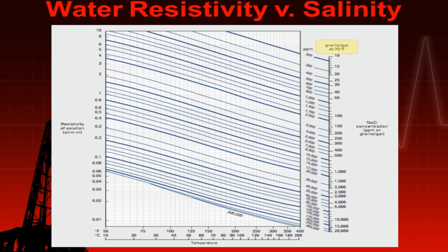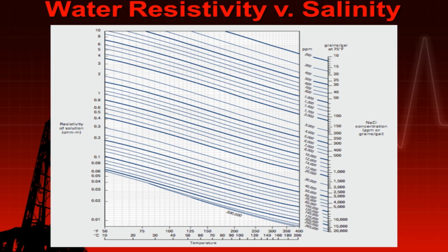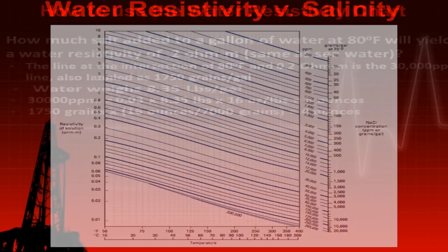So over here you've got this in grains per gallon. So I looked it up. I don't remember this very frequently, but 7,000 grains is a pound. So if you're down here, this is a pound per gallon. And so that gives you a resistivity of 0.1 ohm meters is what that would be.